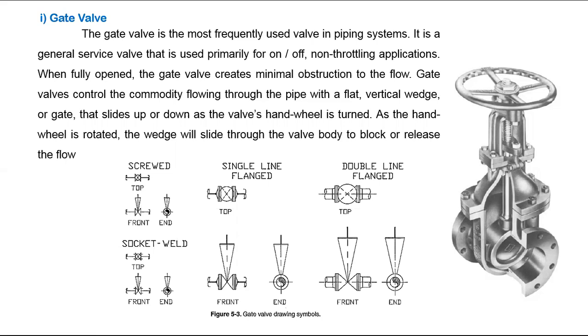We have to consider the diameter. 12 inch means you have to show 300 mm OD. 100 means you have to show 100 mm for the double line. But in single line you show only the center of the pipe. Because of your time availability, you can use single line or double line, both you can use. If you have more time, you can draw a double line diagram.